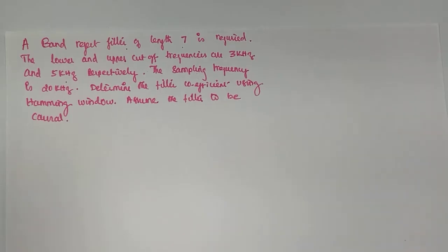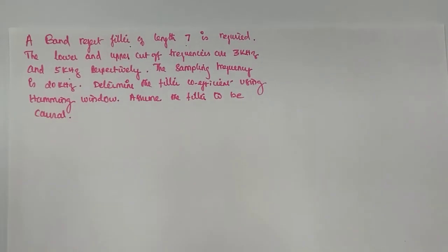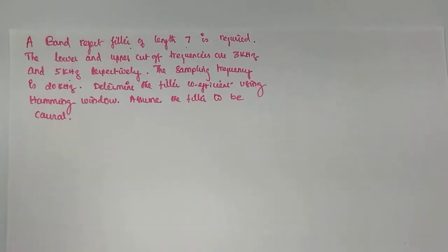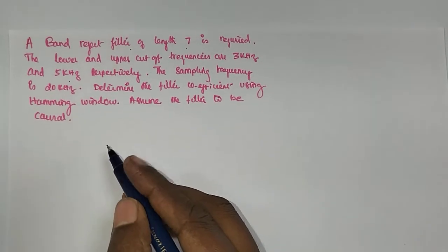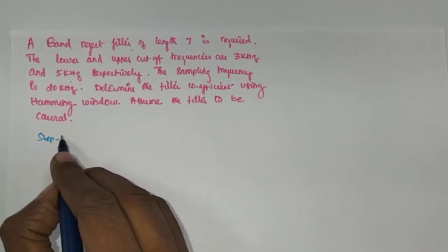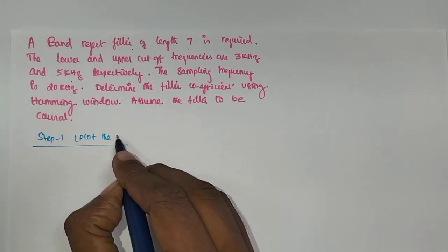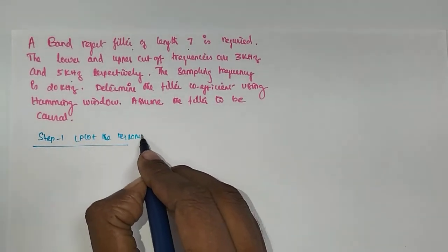So for this problem, the given cutoff frequencies are in hertz. You have to convert them into radians per second. That is step 1, the conversion. Then plot the response. Step 1 is to plot the response.